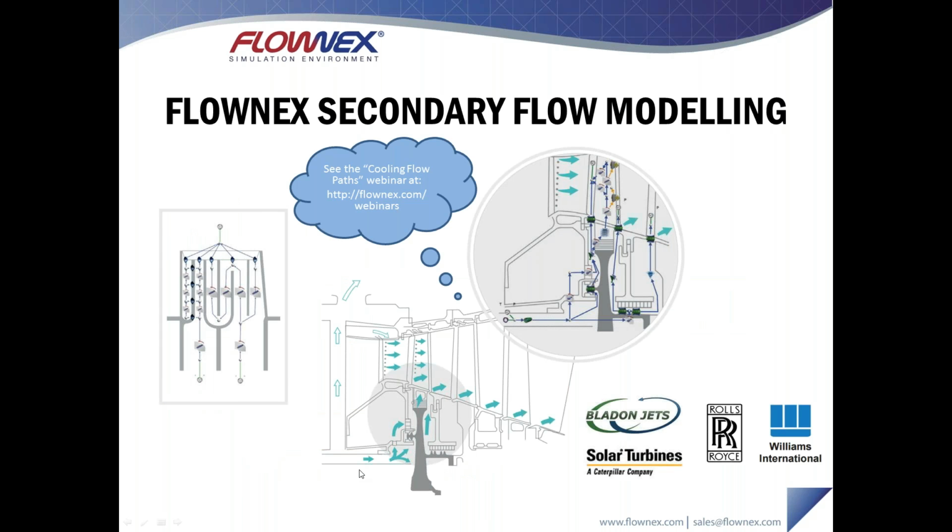All right, so inside Flownex, we have a couple of different applications in terms of cooling flow or secondary flow modeling. We have the blade cooling flow, which I'll be focusing on today, but then there are also other applications when it comes to additional secondary flows inside of turbo machinery. So be this a tap-off point from a compressor stage and the routing of that flow into a turbine stage. This flow can then be modeled by a sequence of one-dimensional elements and basically solved in this one-dimensional environment.